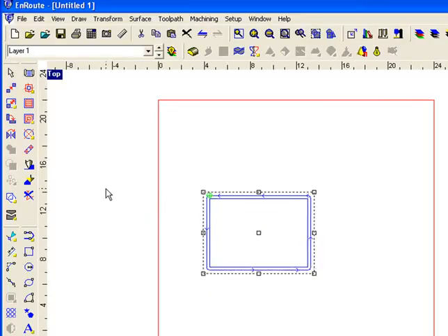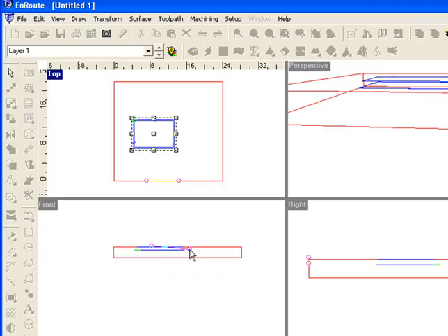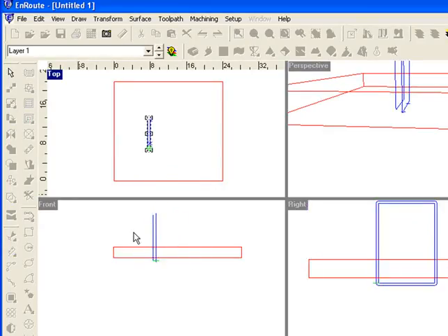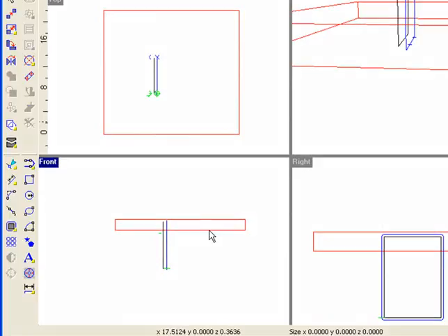But let's say I want to rotate that toolpath so that it cuts sort of going along the x-axis. So now the tool would cut along the x-axis. And if I position it, say, down into the plate, and in this case you can see that the start point is kind of in the bottom corner of the part.